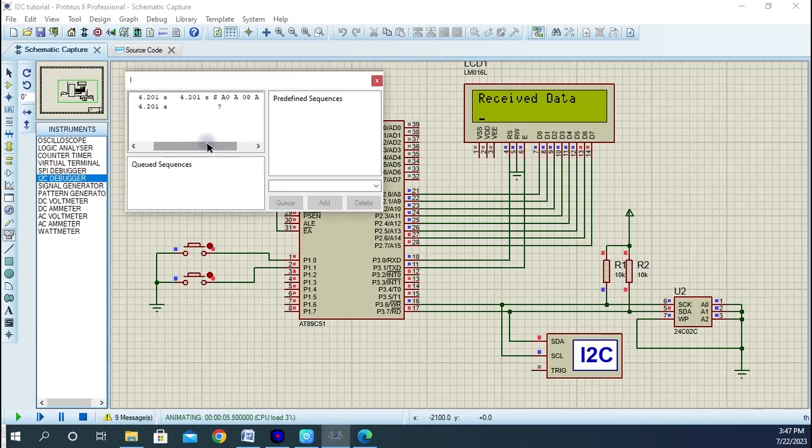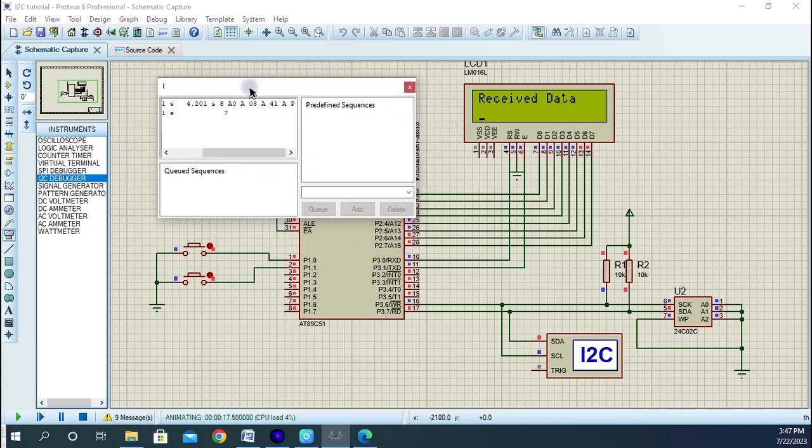I saved the value A, and remember, like I told us earlier on, there is every need for you to go and learn hexadecimal conversion. That value we saved, the alphabet A, this is the hexadecimal value of A. 41 is the hexadecimal value of A in capital letter. When it is in small letter, the hexadecimal value of a is 61. Okay, let's read. This is the value we saved. I have read it. 41.